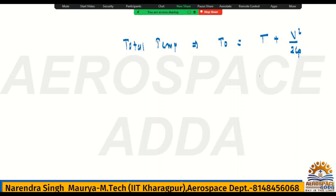Even though they have given the inlet temperature, or you can say the atmospheric temperature, it's your choice, T naught equals Ti plus Vi square by 2 Cp. I wrote it in reverse, no problem.